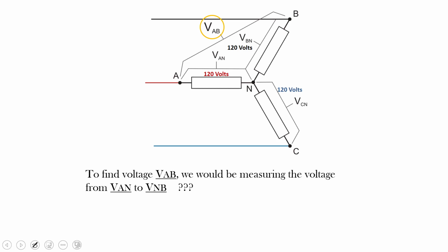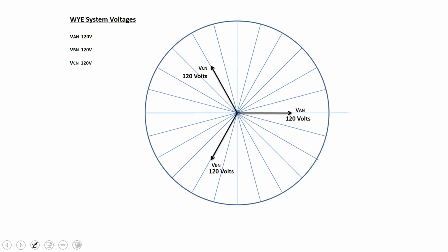Okay, so as we said, for line voltage VAB, we walk from A to N and N to B. So VAB is equal to VAN plus voltage NB, at their angles, and we'll get line voltage VAB. So where's this N to B thing? Well, we have voltage VAN. It's on our reference. It's right here. We have that one in our formula.